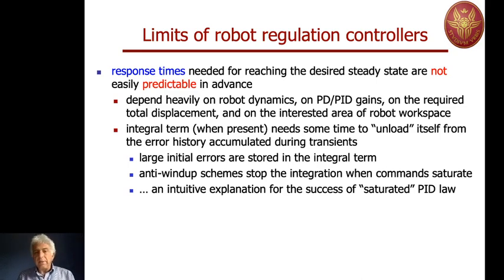This is why, even in the current automation practice, not for robotics, there are many anti-wind-up schemes that stop the integration when something happens. You can start integrating only in the vicinity of the destination. This could be one idea, actually quite interesting. Or if your commands during the initial transient, and we will see that this is another issue for this type of controllers, saturate, indeed there's no sense of accumulating integral error when we are in saturation.